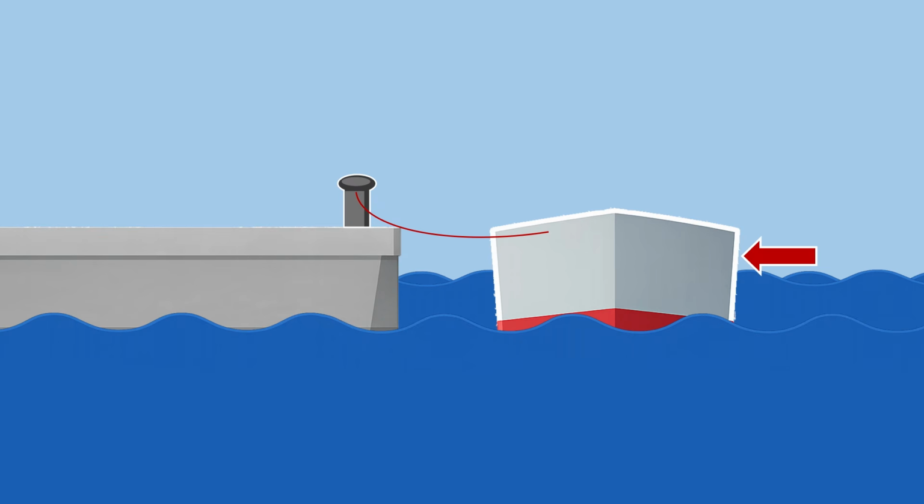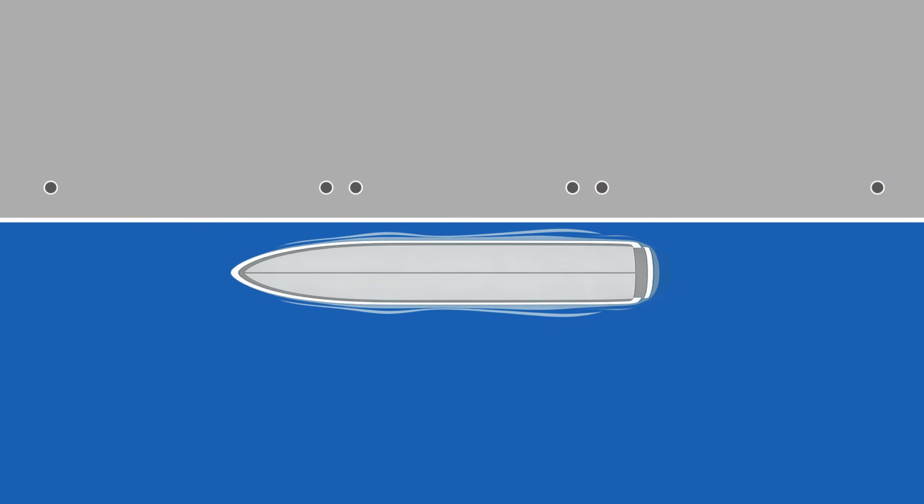The wind acts on the ship, not directly on the quay. The ship transmits the wind force through the mooring system. A typical mooring arrangement includes bow lines, breasting lines, springs, and stern lines, each serving a specific purpose.